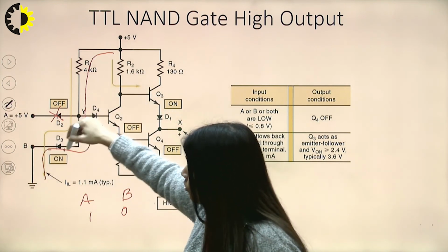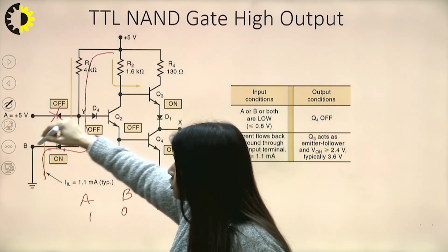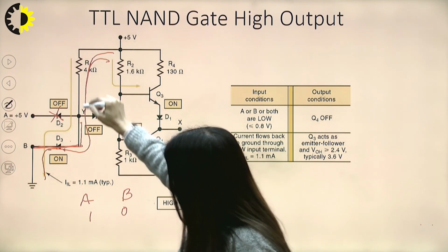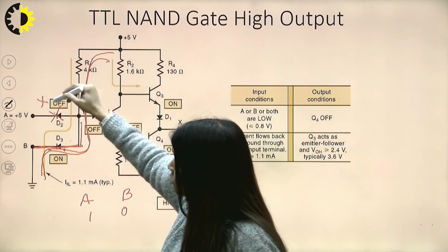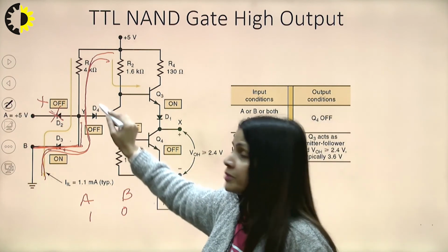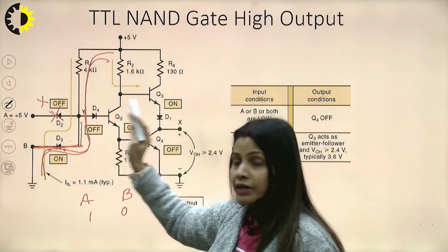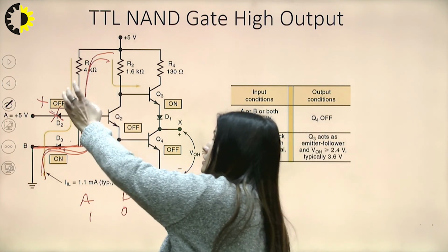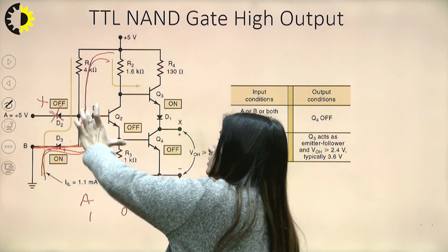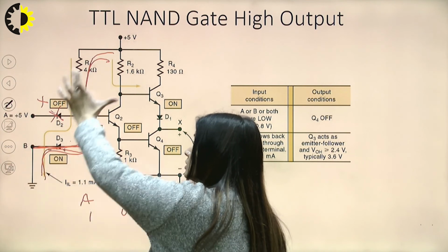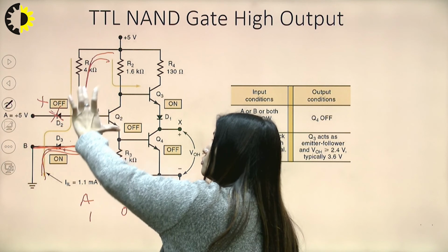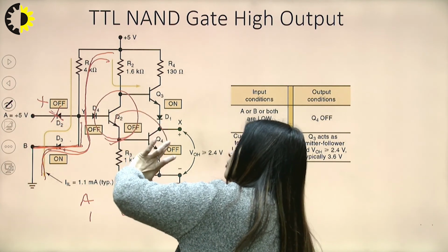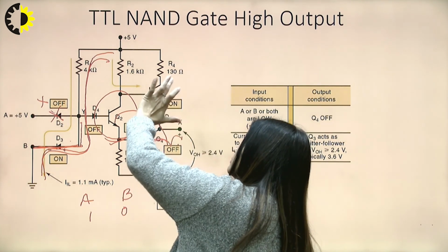this has no resistance path. This G3 is short circuited. This is going to be a short because this is forward biased diode D3, so all the current will flow into this. No current will go here because this is off, and this is a high resistance path. Here it also gets some resistance because of this diode. So D4 is not going to draw current. If all the current is going through B, or due to the short circuit across D3, this will make Q2 off, and if Q2 is off, Q4 is also off, and if it is off, then this one is on, and